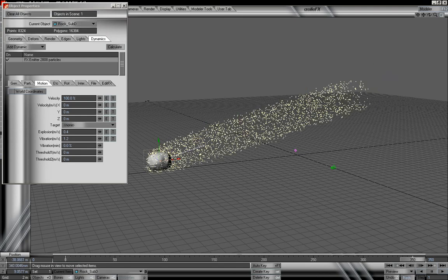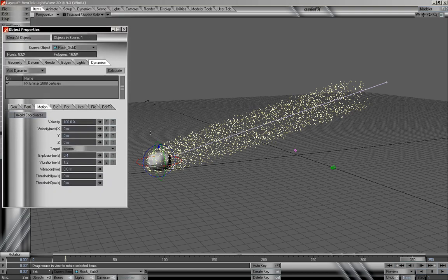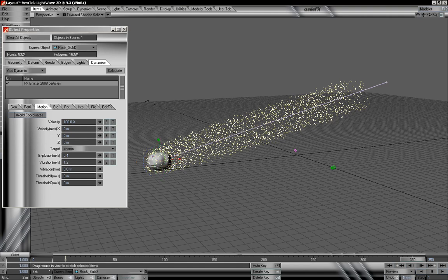So let's go ahead and add a little bit of rotation towards the end or on our last frame to make this object kind of rotate throughout the scene. So we'll go ahead and switch to our rotation, which I'm using the scroll button for on the mouse. Otherwise you could just hit Y on the keyboard, and T will allow you to move, Y to rotate, and then we can also use the scroll button in order to change back and forth between each of the different transformations.